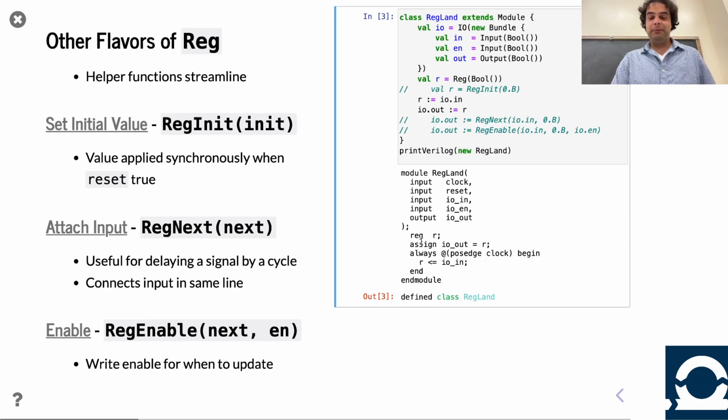First of all, if you're learning Verilog, you may be surprised to learn that reg does not mean register. You can use reg for things that are combinational or registers. And a register happens in Verilog when you use a reg in a very particular way with an always block and the CAD tools infer a register, right? The synthesis. I mentioned the reason this happens is because Verilog predates synthesis for hardware generation. It was originally a simulation language, and then when people were already using it, they later learned how to work backwards and figure out how to infer what the hardware should be. So if you're taught Verilog, you're taught these very idiomatic ways to write registers: reg r, always @, and then using the right type of assignment inside here.